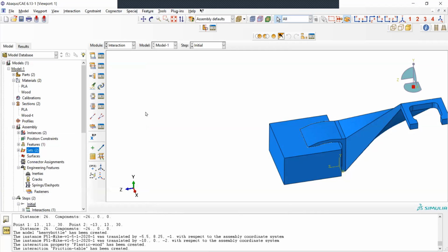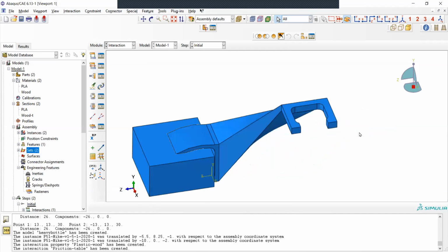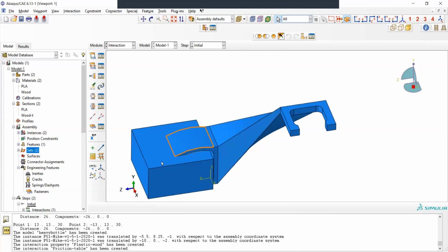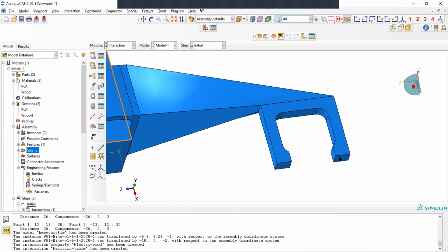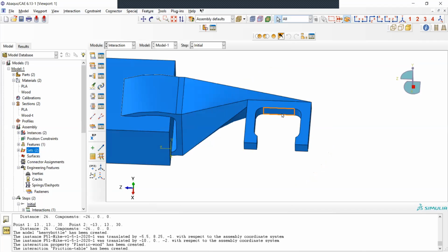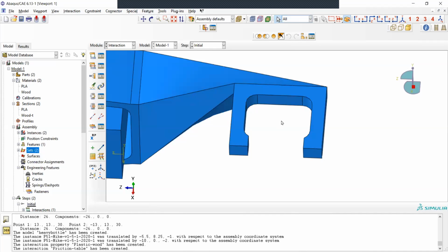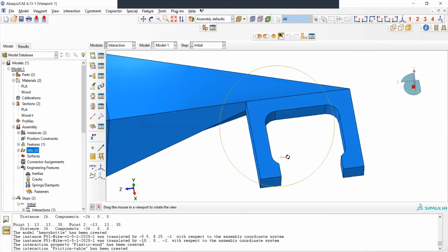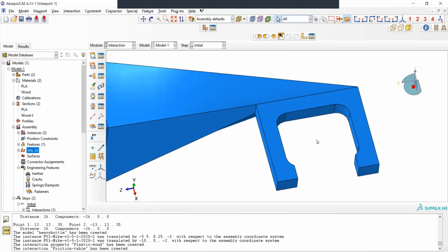I'm going to move a bit faster now. So this is for the friction interaction. For the bottle, now I have a contact between the part and the table, but where does the bottle go? I'm not going to draw a bottle and apply forces. I could, but it's not necessary. I assume the bottle is not going anywhere. I assume there's a constant friction in that location. To do that, I need to create a point, and you can see here there's something called the reference point. I don't need to have it exact, but I need to approximate it. It's better to have it somewhere here where the bottle should be. So I'm going to try to find a location for it.